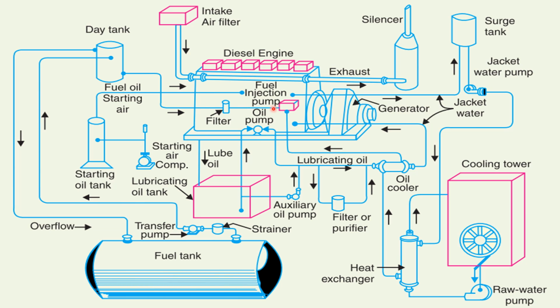After this, we are going to look at this intake. The air is taken in from this air intake, and fresh air is taken in, and then it goes through this air intake filter, and then it enters the diesel engine in the different cylinders via the engine manifold. Inside the engine, this air mixes up with the fuel and rotates the piston of the engine, and then the byproducts are sent as exhaust to the silencer, and they are emitted into the atmosphere.